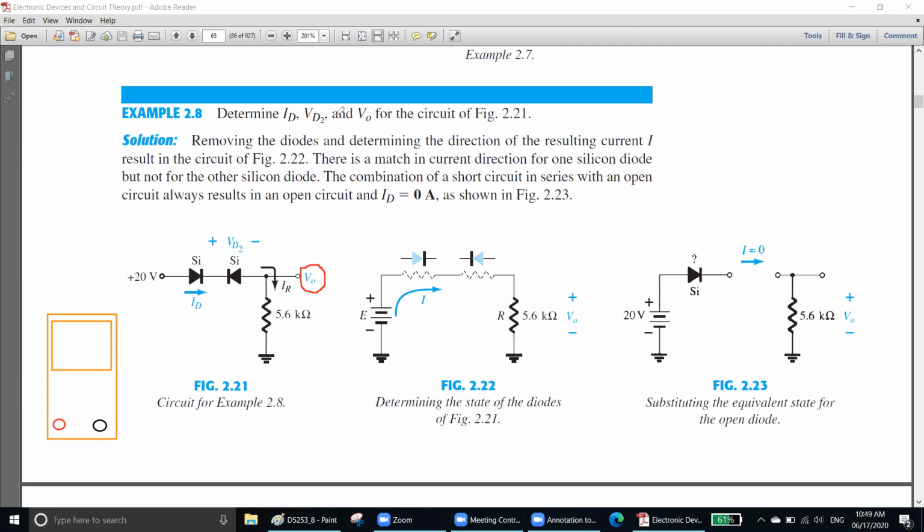What we do is take the plus, the red one, and put it here. And then we take our black pin or the black wire and put it here. So what happened? The multimeter subtracts the voltage from these and to these, that means these minus these. They subtract and give us a result. Understood? This is called voltage difference, finding out the voltage difference.